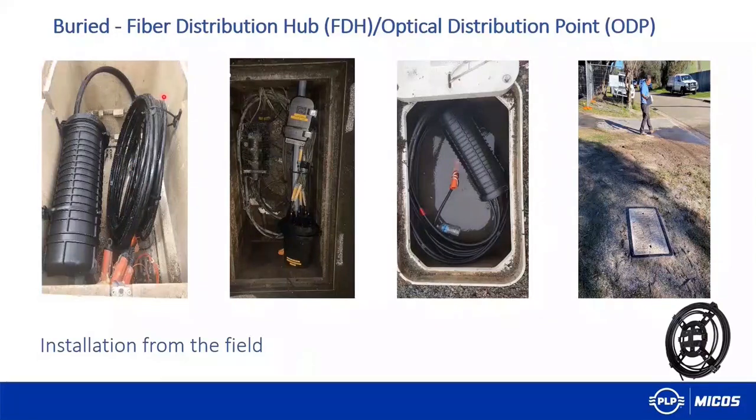at least 10 meters here, and you go with the closure inside the installation car, and you can do the job inside, where it's sometimes warm and dry, so there is no rain, no frost. Yeah, so in those two pictures, you can see the standard dome closures, and over here you have special closures. For example, this closure, a little one, is maybe only 20 centimeters high. It's able to connect and splice up to 48 customers. So from this little closure you can do, for example, 12 drops directly to the houses.